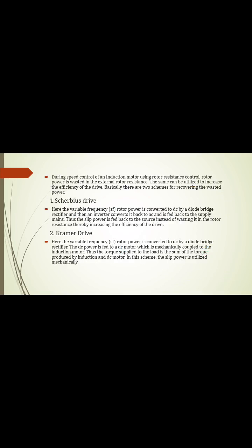During the speed control of induction motor using rotor resistance control, rotor power is wasted in the external rotor resistance. This rotor power can be utilized to increase the efficiency of the drive. There are two schemes for recovering the wasted power. One is the Scherbius drive and another one is the Kramer drive.